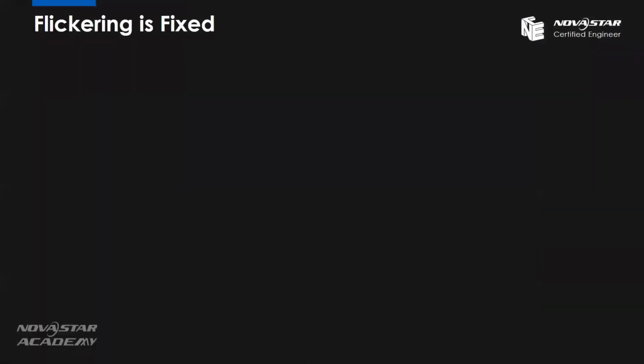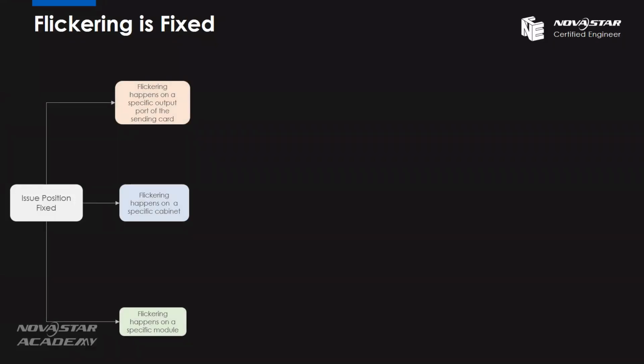First, if the flickering position is fixed, which means the flickering is not random and only happens on a specific area of the screen, it could be one of three situations. The first one, the flickering happens on specific output ports of the sending card. The second one, the flickering happens on a specific cabinet, or you can consider it the receiving card. And the third one, the flickering happens on a specific module. Let's see them one by one.